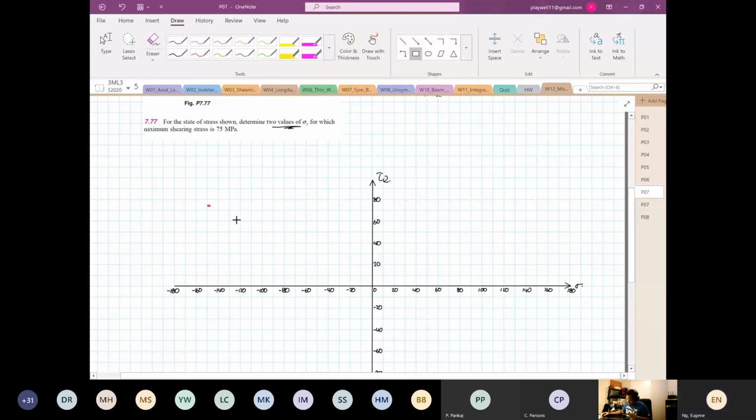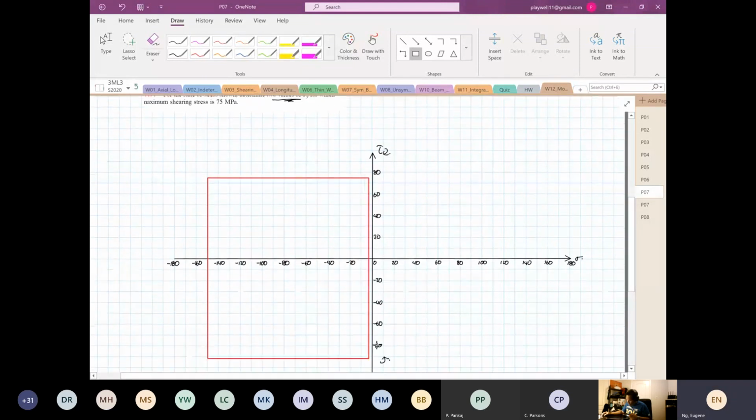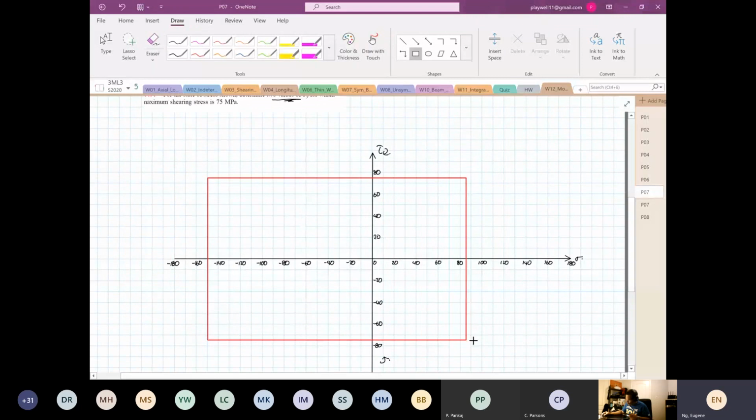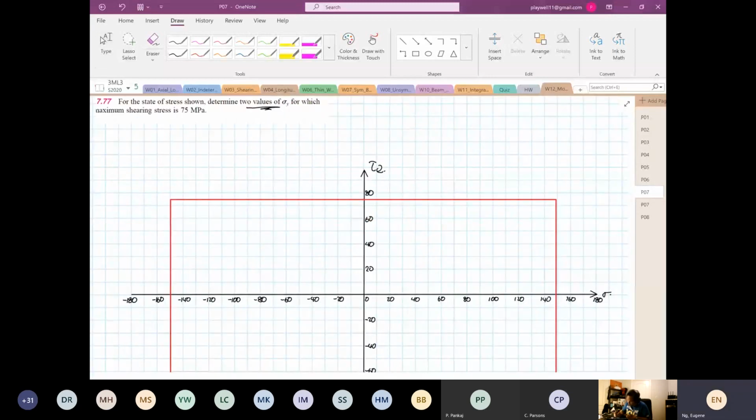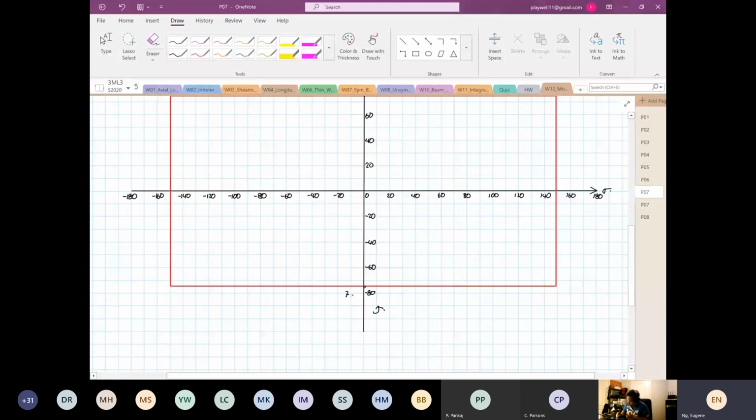So there you go. The outside of this box is known as the demilitarized zone. You go there, you die. So this is the box. What we have just done down here is incorporate the yield strength in normal stress and shear stress into a 3D Mohr circle. This is real life now. So what do I mean? We know the top down here, this value is 75 megapascal. Down here is also 75 megapascal.